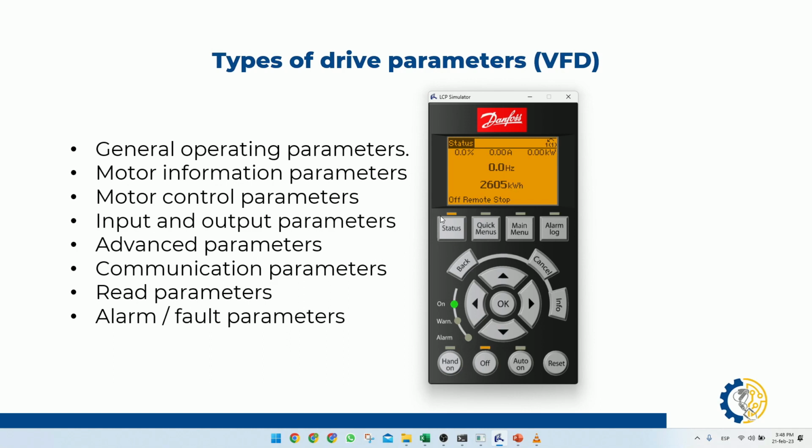For example, I'm going to add auto on, and this is our current speed. So it's simulating that it's running at 13.9 Hertz. So it's not getting our commanded speed. Now it's all the way down to 9.6 Hertz. So this is its amps, or its current, and on this side we have our potency. So if we stop this, it's going to tell us in real time its speed and how it's decreasing. Okay, that's what I'm looking at. So that's where it stops, and that's the real speed, the current speed.